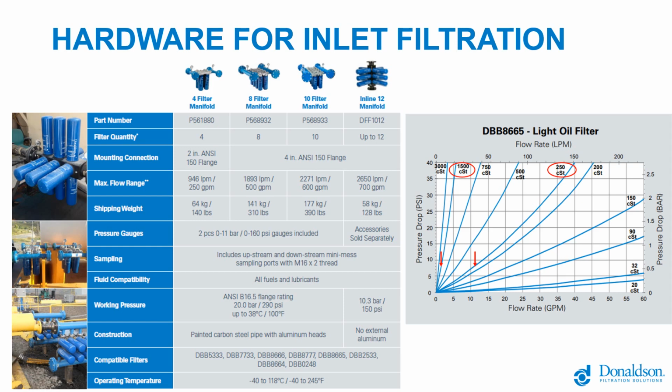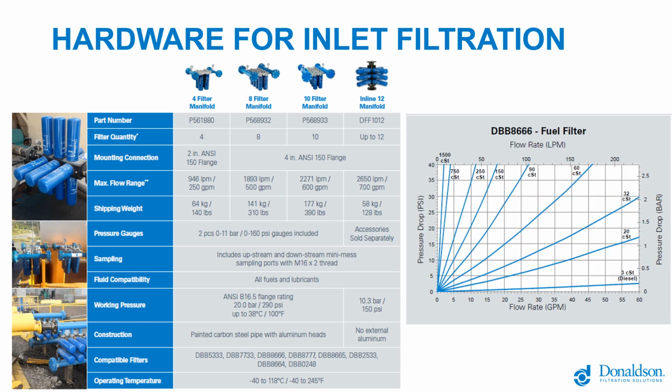In operation on equipment, most oils are in a viscosity range where you can't really mess up picking a filter and going with a tighter filter and not having an issue. In this bulk and ambient condition filtration, actual temperature and its viscosity of that fluid is critical. It's not uncommon for people wanting to over-filter the fluid and say, well, I want to get it a little bit cleaner just because that's what I want to do and it's the right thing to do.